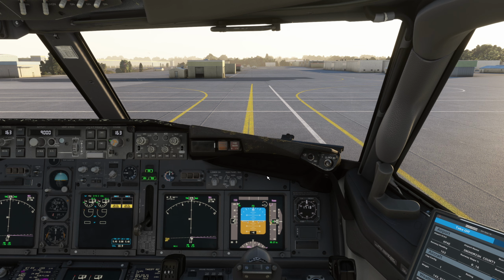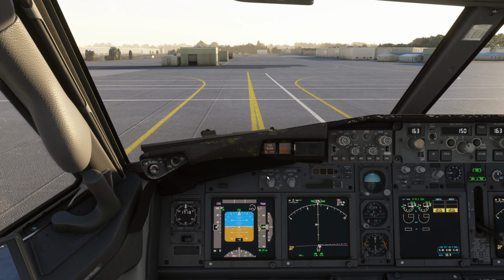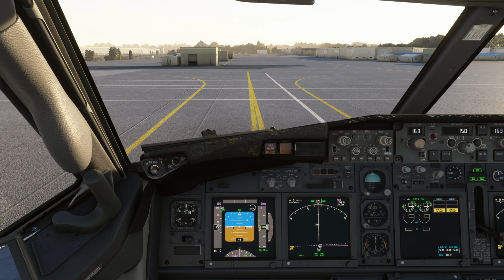We can now take a second to review all the items and run the pre-flight checklist. Prior to running the pre-flight checklist, we would discuss the plan for the departure with the other pilot and ensure that we're all on the same page for nav aids being used, as well as which modes can be expected on the autopilot. Once the briefing is complete, we'll run the pre-flight checklist.